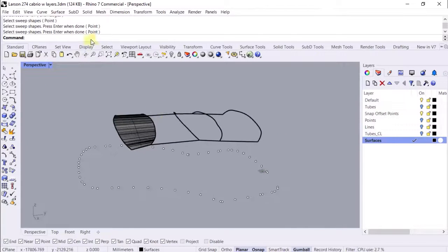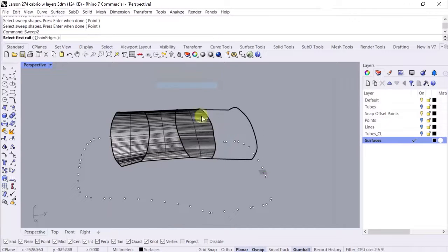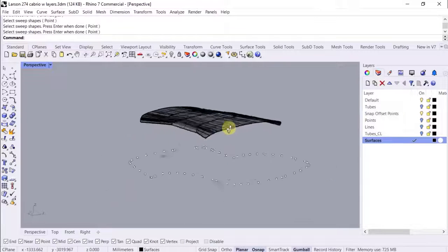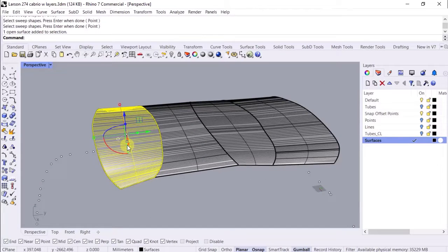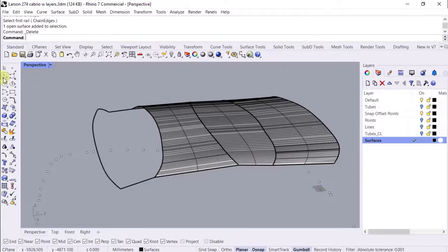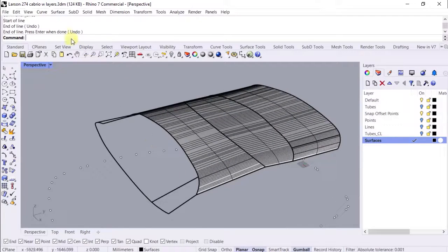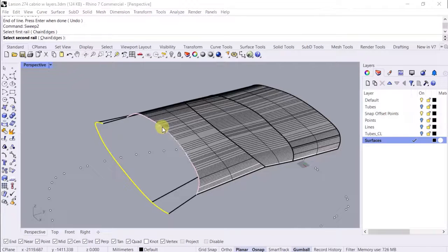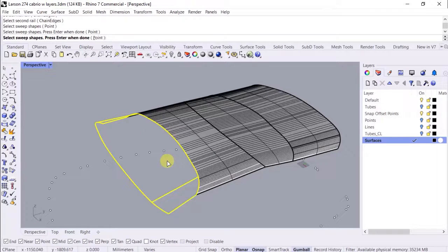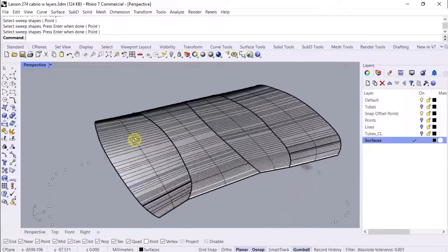We continue the process of using Sweep To on each Bimini section. If there's a twist in the result or something about the shape you don't like, you can add additional sweep lines to the surface. We will delete the surface and add additional line segments. We turn off the knot snap so we can add the line where we want along the curves. We add 2 line segments. Then, using the Sweep To command again, choose the rails and 4 sweep shapes. This method can be used to control twists in the surface.